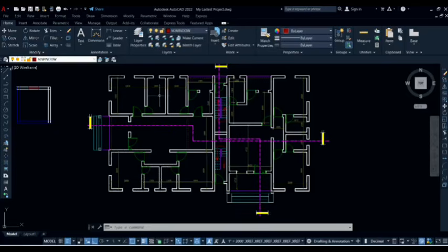So it allows us to isolate the useful layers. So maybe when we need to keep an object, just isolate it, we hide it, and then we clear the other drawings on the screen and bring the layers back. That is, we are going to unfreeze them. Layer isolate is useful when we are working on a complicated drawing and want to focus on one category of objects. So that is it.